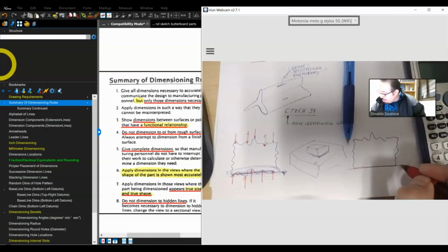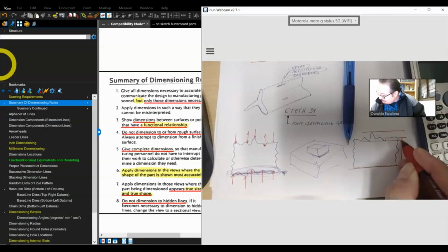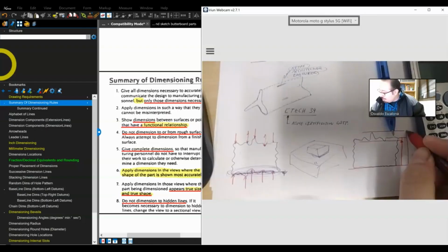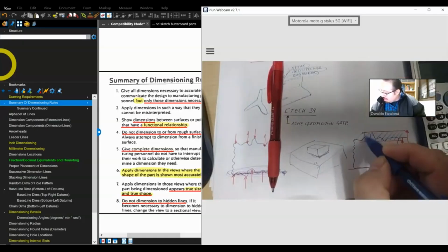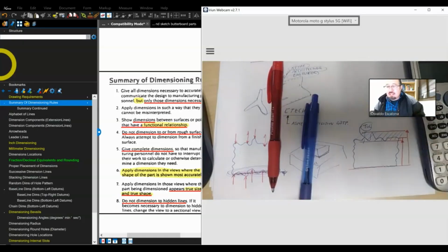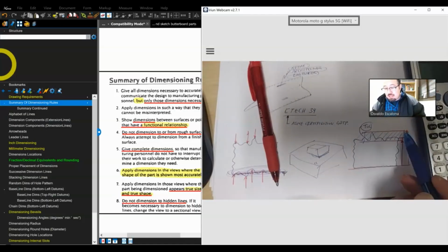And I can measure from here to there, and from here to there. What is this region? This is where I told you guys the tolerance. This is the leeway that you give to the manufacturer. I can make it as small as this and as big as that. When you make it, you better fall within those limits.